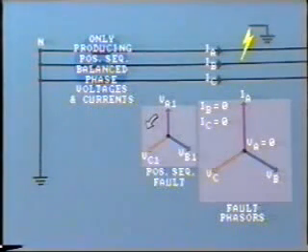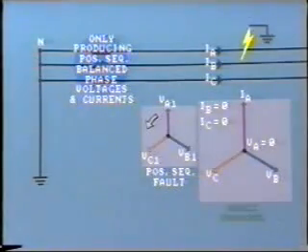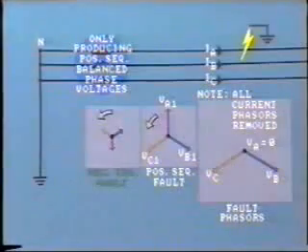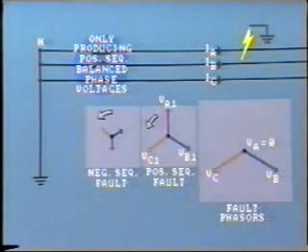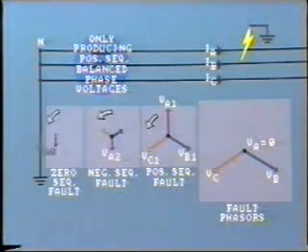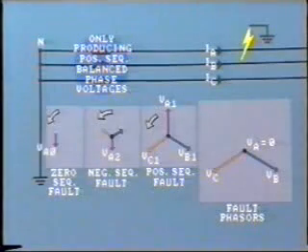So once again, let's see how the positive sequence quantities are transposed into the unbalanced voltages and currents at the fault. Now remember our previous conclusion. Any unbalanced fault has negative sequence components acting on the positive sequence quantities. Now where a ground fault is present, we need to add yet another set of components. First, let's look at the voltages on line A. At the fault, VA equals 0. VA1 has been canceled out by the negative sequence voltage VA2, and the missing component, which we call VA0.